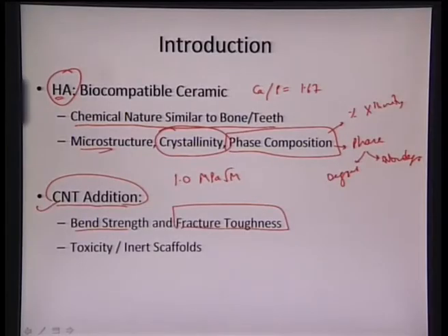But people have seen some effects of irritation or toxicity, whereas another group has seen apparent precipitation onto the carbon nanotube surface. So we have to carefully weigh these two aspects before we take them for clinical trials. Ideally we are adding carbon nanotube as a reinforcement in the hydroxyapatite to improve its fracture toughness. We also need to confirm whether these scaffolds will be toxic or cytocompatible. So we need to take that into consideration also.